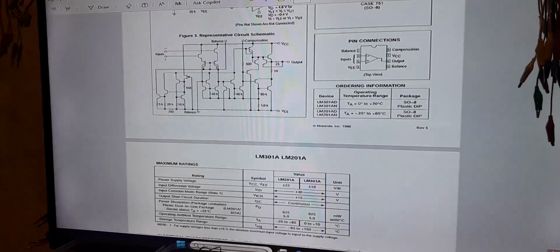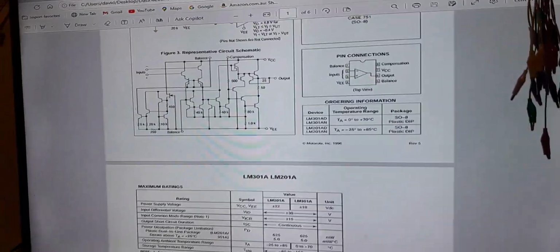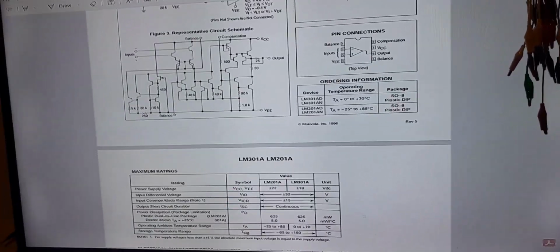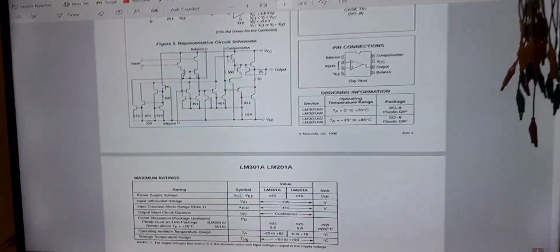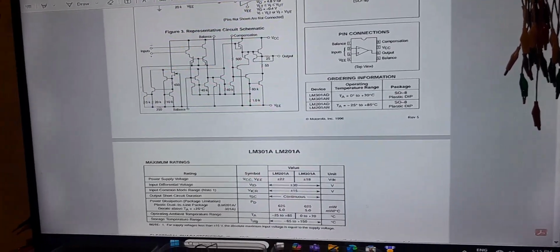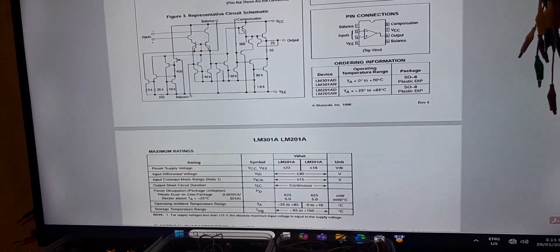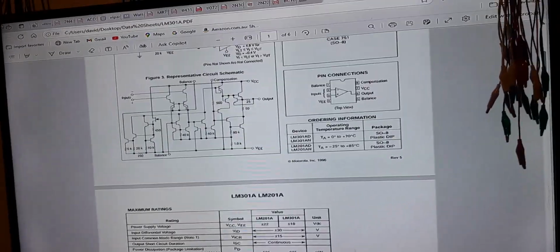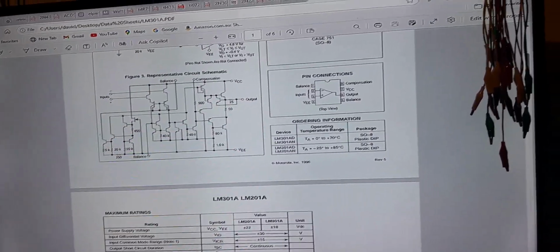I could be wrong, but JFETs are very sensitive devices. There is a linear region on them, but it's not hard to get them outside of that, and oscillation, all that sort of crap would do that, which would then make the whole op amp do weird things and go out of range, like what the panel meter is doing. So that's why I kind of think it's something more to do with that.